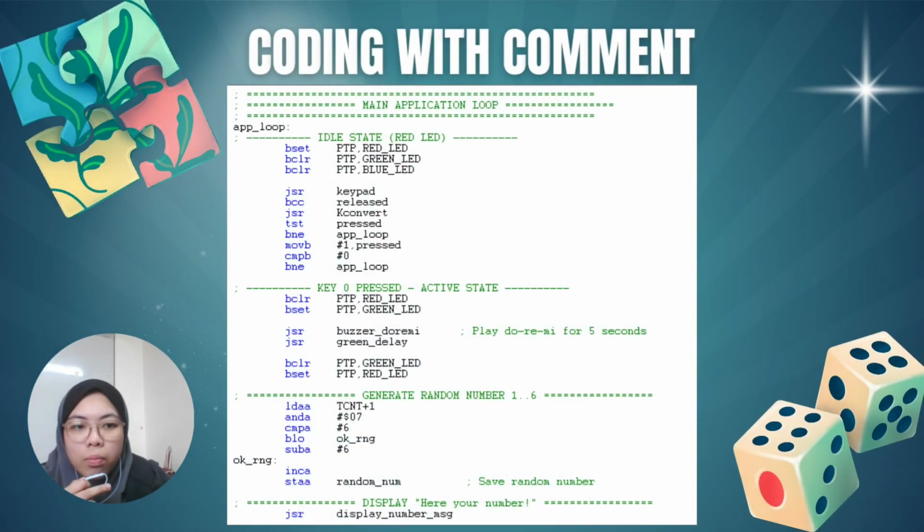This slide shows the main loop operation in this coding program. Idle mode, red LED on, waiting for keypad input. Key pressed, green LED on, buzzer activated. Generate a random number 1 to 6 using the timer. Display the result and return to idle. This loop controls the system behavior. It waits for a keypad input, activates the visual and sound indicators when a key is pressed, generates a random number between 1 and 6, displays the result, and then returns to idle mode.